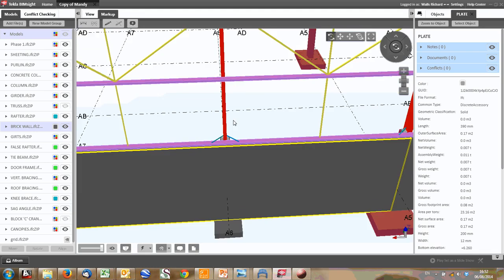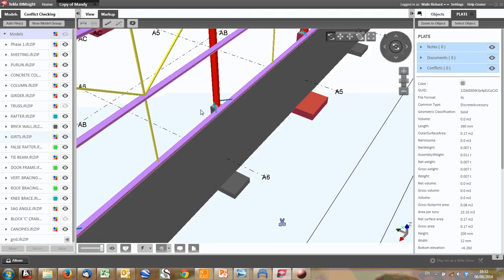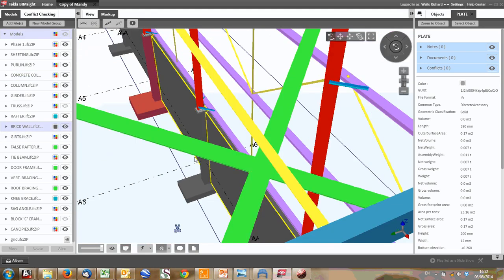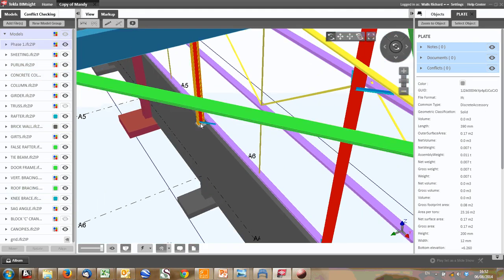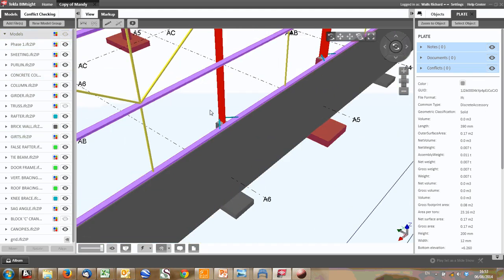So here, the load will then be carried by a cantilever. This column, this concrete column, you can model as a cantilever. It's fixed at the bottom, pinned at the top, or free at the top, with a horizontal load, which is the reaction from that. And that way you can size the column and size the base without too much difficulty.